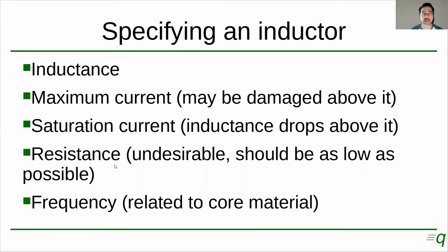And the last one is related to the frequency. Depending on the core, it may be good up to a certain frequency. Remember when we were having the boost converter circuit, we said we would open and close that switch many times per second, right? So there's a frequency associated with that. And some cores are good up to a certain frequency, and some cores behave well at a higher frequency. So you have to ensure that the coil will be working properly at the frequency you want it to work.